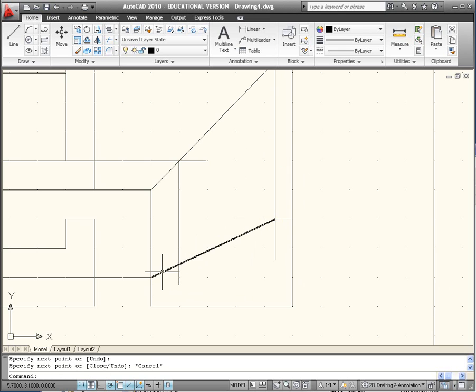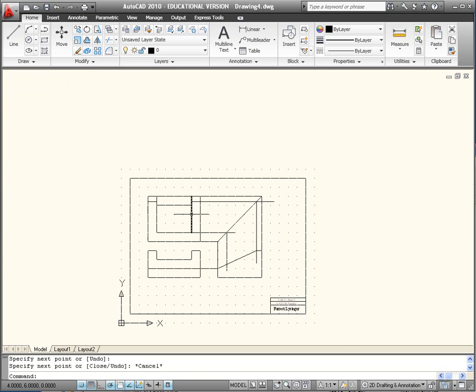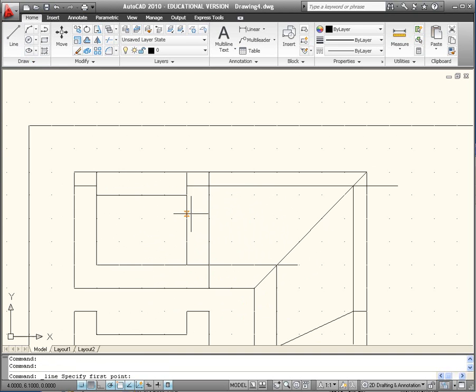So my angled face that's on my part goes from here to there. These lines here show me where to place the hidden lines on the inside. The one other feature I haven't brought down yet from the top is this one. So this will have some hidden lines associated with it.